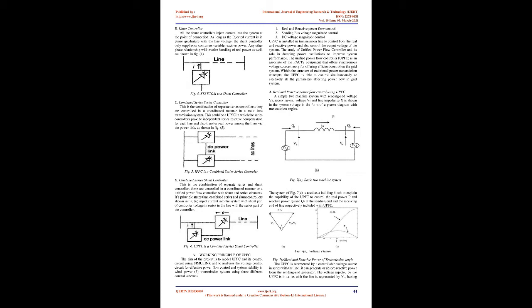Unified Power Flow Controller. FACTS controllers are a family of power electronics based devices. Among the group of these controllers, the Unified Power Flow Controller, UPFC, is termed the best FACTS controller. It acts like a multitasking controller, which can perform several functions at any instant, such as controlling the transmission voltage, impedance, and active and reactive power, providing benefit to the power system.